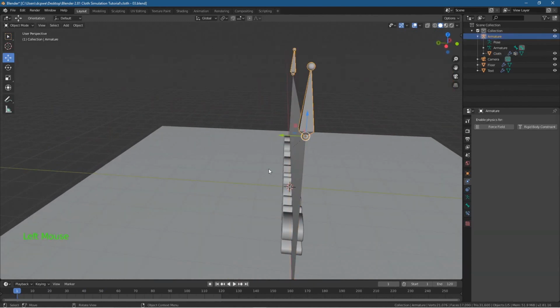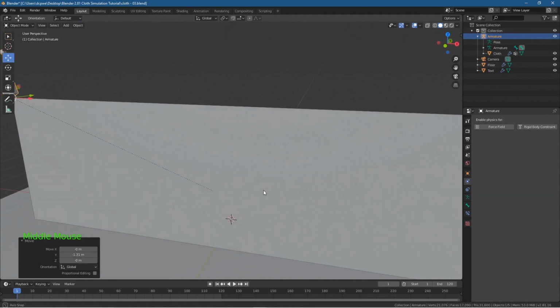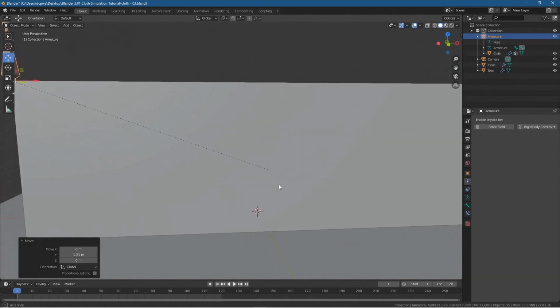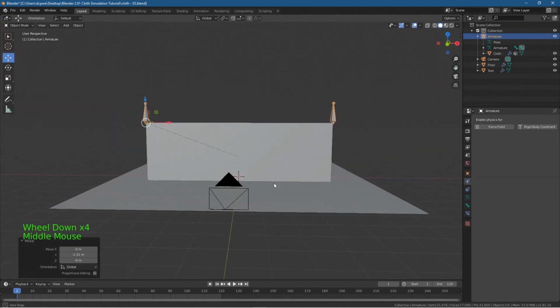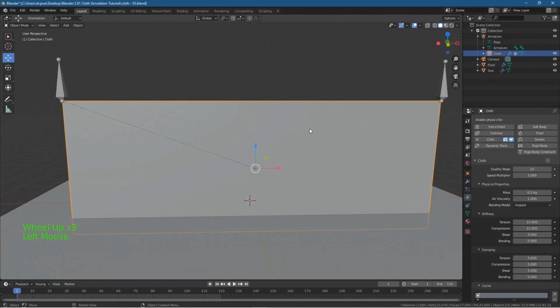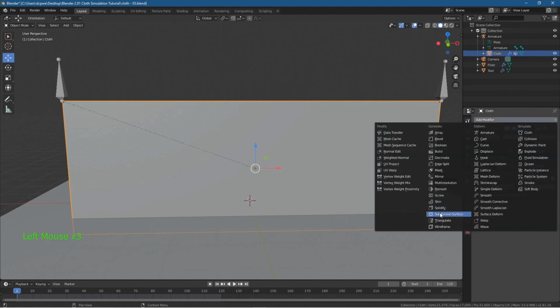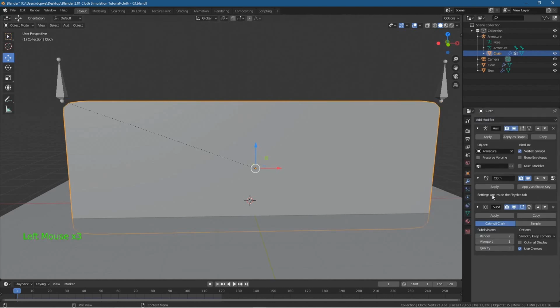So let's click on the armature, let's click on the move tool, and let's bring that object forward in front of the text. We want it to be sitting in front of the text, not behind it. And what we want to do, let's see, we want to subdivide this material. So let's click on it and go to the materials modifier properties here, and go to add modifier. Make sure you click add modifier and subdivide here, and set the subdivision to a value of 3 here.